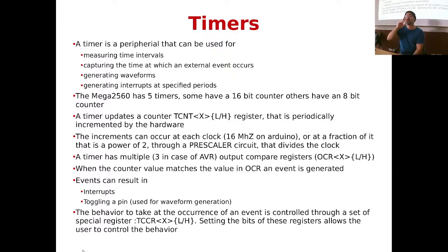In addition, each timer, now this is the big complication, but you will have to see the code actually. Each timer is attached to special registers which are called output compare. What is an output compare? An output compare is a number that has to contain a time, right?